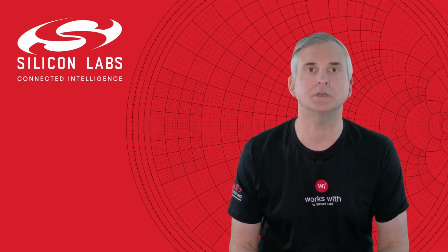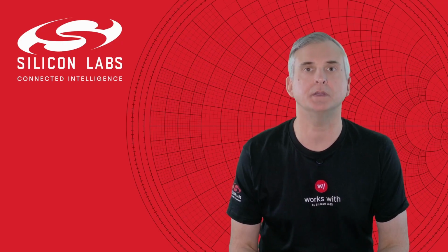All these components offer software APIs, removing the need for you to develop your own, and in some cases including them will add supporting configurations too. Adding a BLE service software component will also configure your GATT database, while adding a peripheral component will configure your pins appropriately. And you still retain flexibility over these when using them via the configuration settings available in the software component.